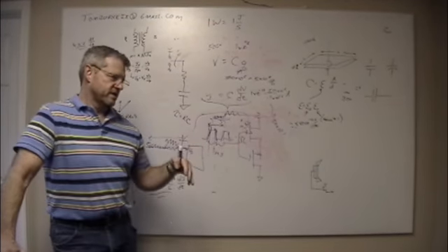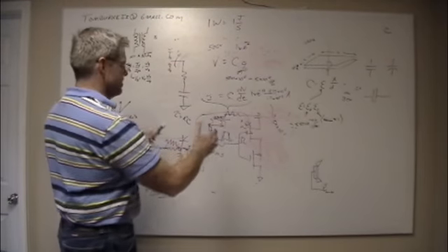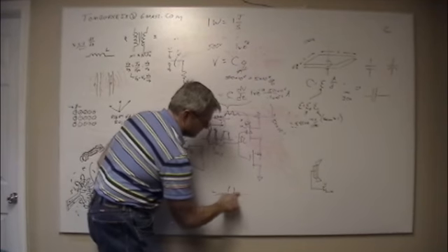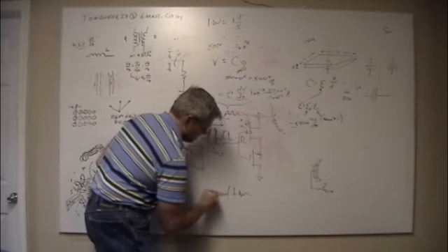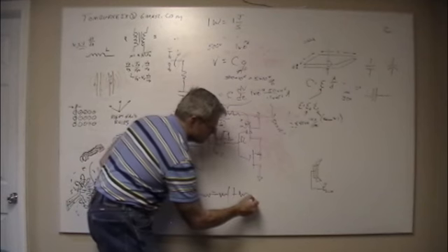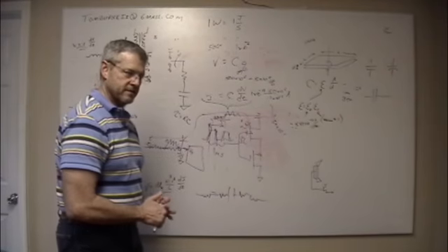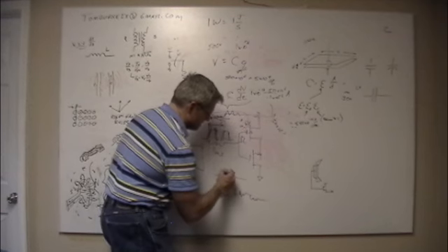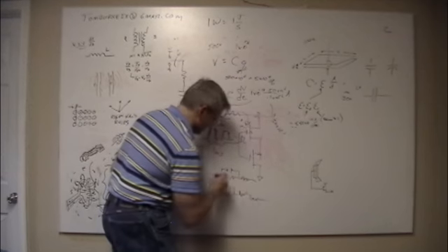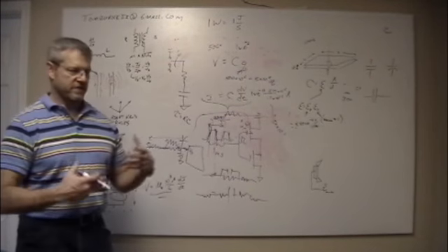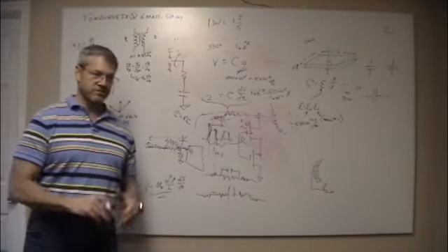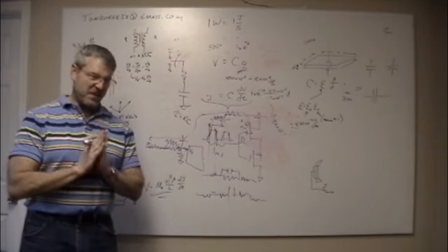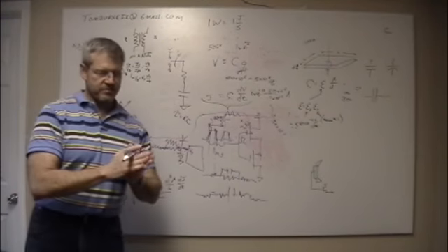There's a little bit more to it than that because you've got the inductance. If you look at any of these components, it's not a pure R, it's not a pure C. If I look at a capacitor, I've got this, but then these wires have a little bit of resistance, and they also have a little bit of inductance. So you get a model that looks like that. There's a little bit of capacitance across the resistor, and the wires have some inductance like that. It's really a very complex circuit, and it has a sweet spot where there's a Q, where Q is maximized or minimized, like a peak there. And at that frequency it's resonant and it likes to do something different.